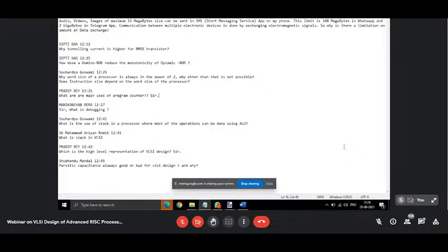Actually, sir, I'm trying to get how pipe can be implemented in the hardware. Is there any shift register sort of thing? Pipe can easily be done. It's very similar to the way you are doing one after another. Let's say the data is going from one stage to the next, in that way, pipe flow. That can be done for data cases using some shift registers.